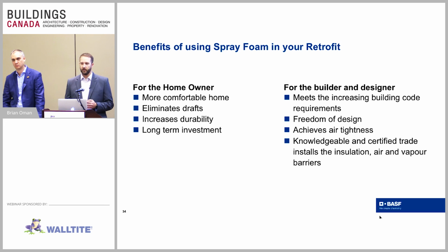Even a passive radon mitigation system will help to diffuse a lot of that moisture potential. Because you have a release point for that moisture as it may build up, it'll find the path of least resistance, which is hopefully either a drainage system or a radon mitigation system.